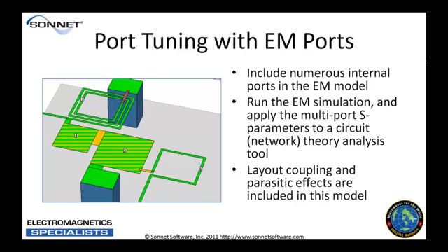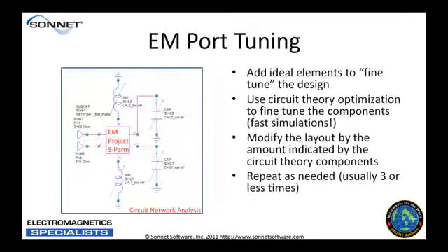And of course the power here is that we're taking advantage of the very accurate simulation yielded by EM analysis to capture both the layout coupling effects and also parasitics that arise from the actual process modeling. So here you can see we take the EM simulation project S parameters here from this box in the middle and then apply a number of ideal tuning elements which will be attached to those special ports from the EM simulation, and then we can leverage the very fast optimization or tuning capability that's provided in network analysis and combine it with the power of the accuracy of EM simulation.